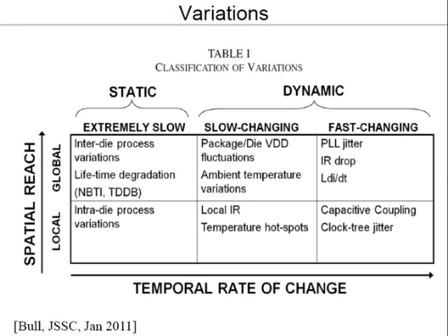Cycle to cycle there is a change in TC. That is called jitter, because whatever is generating the clock is a noisy source. When noise comes in, it can affect the cycle. So those are very fast changes. How do you deal with that? You basically put margins for that, because it's very difficult to track those changes.